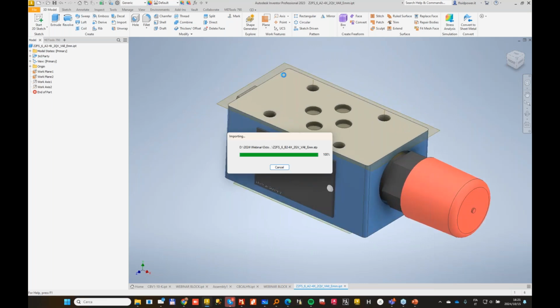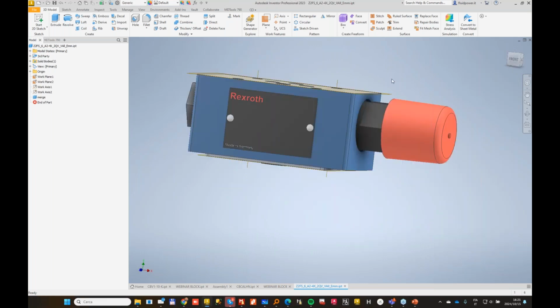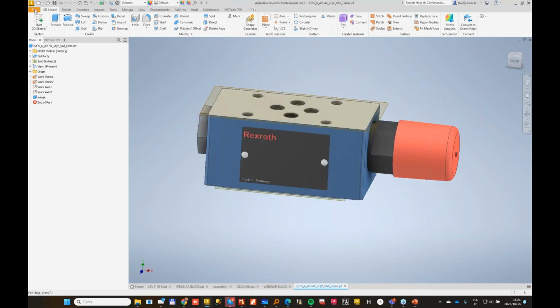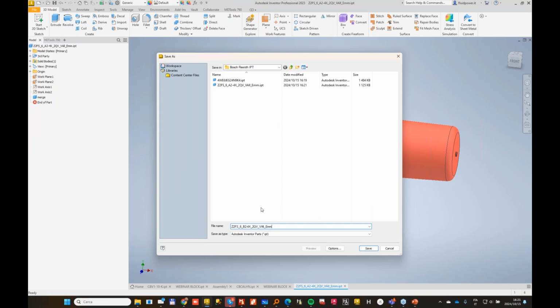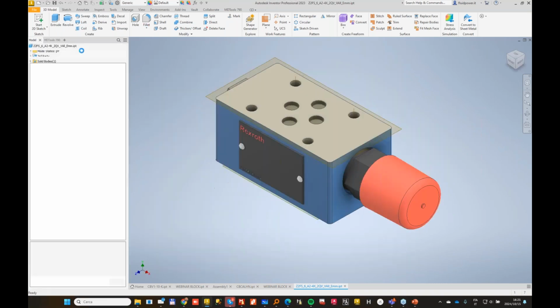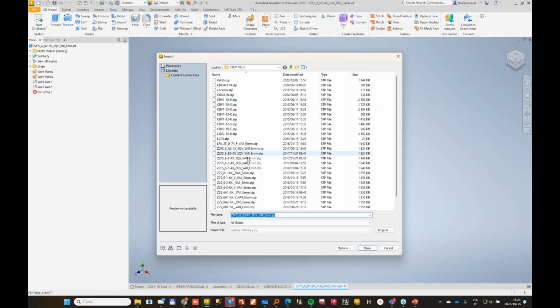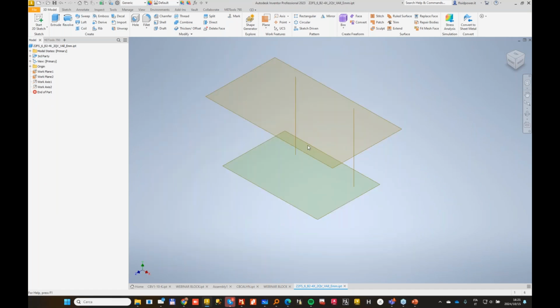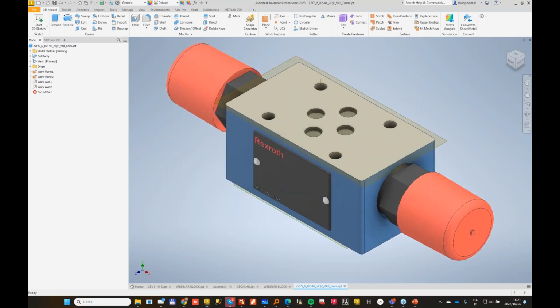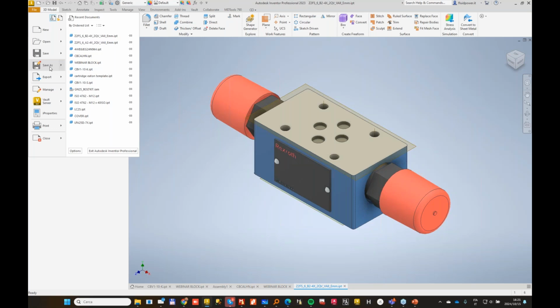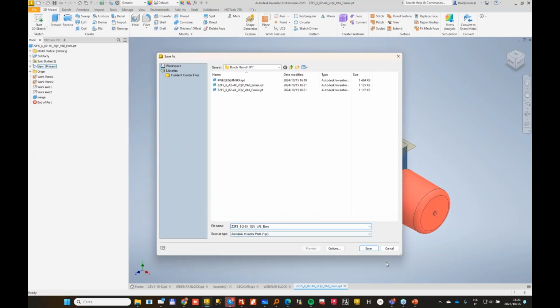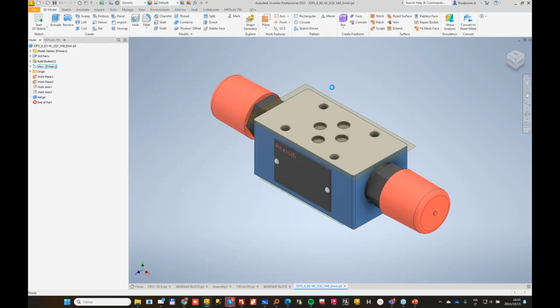Usually manufacturers do things properly. They leave the same geometry, so I can do a save as and saving with this name. Then I can do again, delete and import again. So in this way, by using this technique, you really can quickly instruct several components fitting the same footprint. And now I save as, and save and so on.